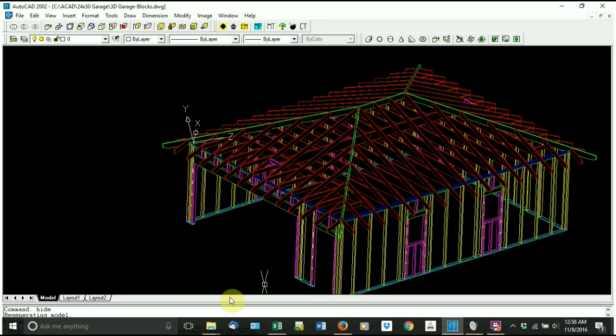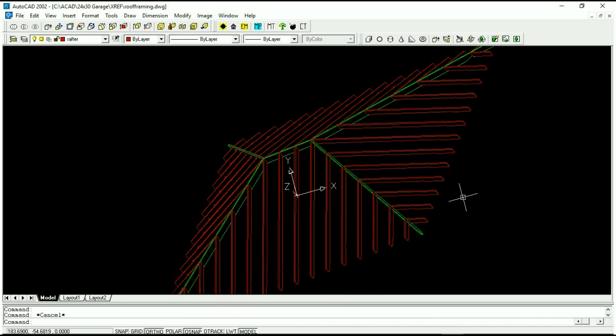So I'm going to go back over here, and before I start in this example, what I'm going to do is make these rafters here on this end as an example of something called specification-based design. Specification-based design is where instead of making the part manually, you use VBA and fill out a user form that has the material properties and the geometric